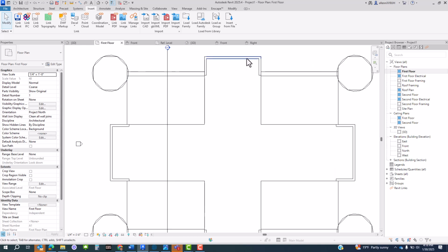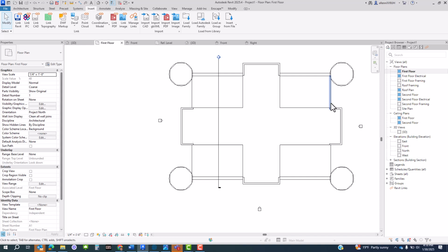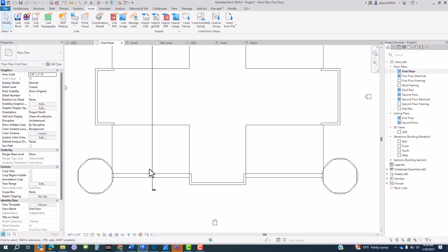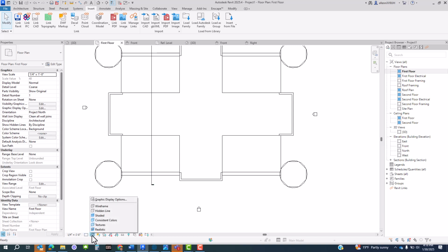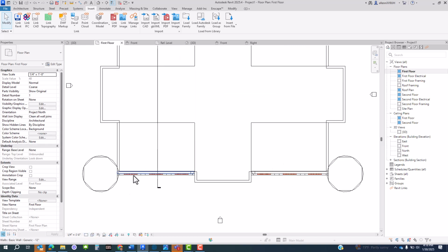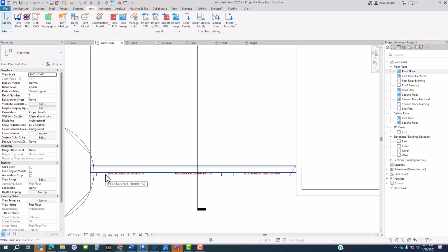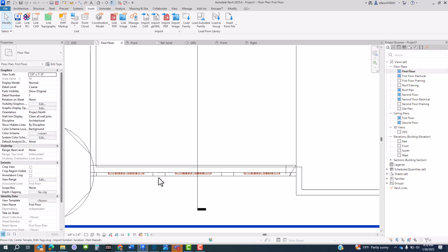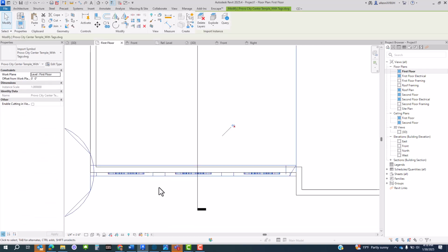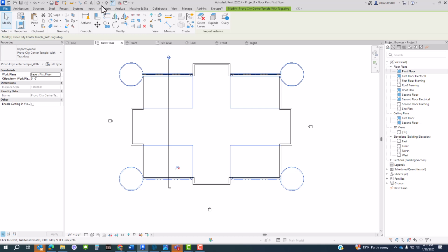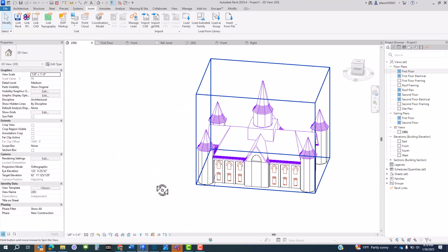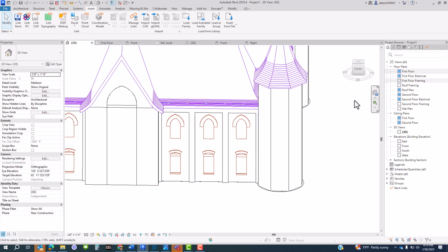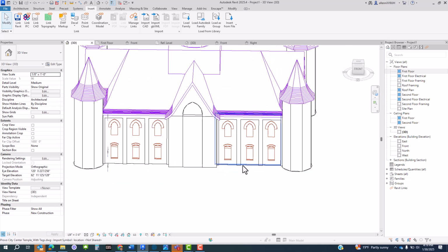It's kind of hard to see if you align out on the perimeter because some of this isn't actually transparent or see-through. And if that's the case, you can always change your view type to wireframe. It gets confusing because there's a lot going on here, but that's the actual wall that I put inside of Revit. And this line out here represents something from the original model. So you can kind of look at it, study it, decide what's what, and that will help you decide maybe what you're looking at in the plan view and what to align to.